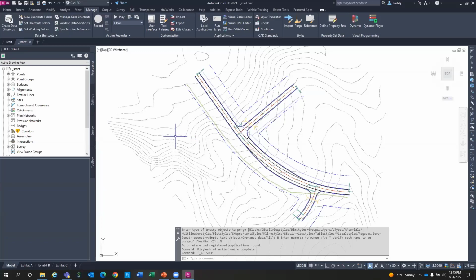Other things, when I work on files, maybe I open this up and somebody else has been working on it. I like to know what's exactly in the file. So I need to know what layers are on, or what layers are in here. If there's anything that's off or frozen, I want to do a zoom extents to see if there's any stuff floating out in no man's land. I want to maybe do unisolate. So rather than go through that process, I would like to automate that so I don't have to do that all of the time. I'm going to make a command that's going to show me everything if I'd like to see it. So we'll create a new command here.